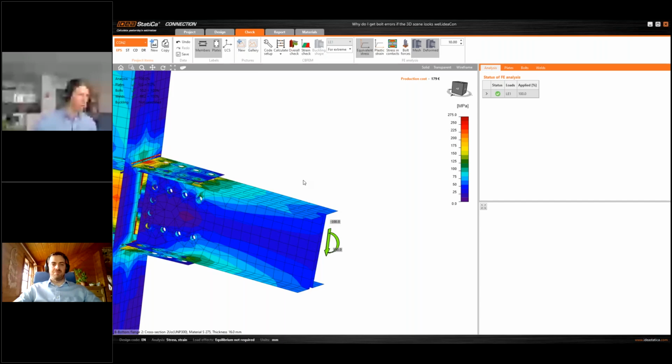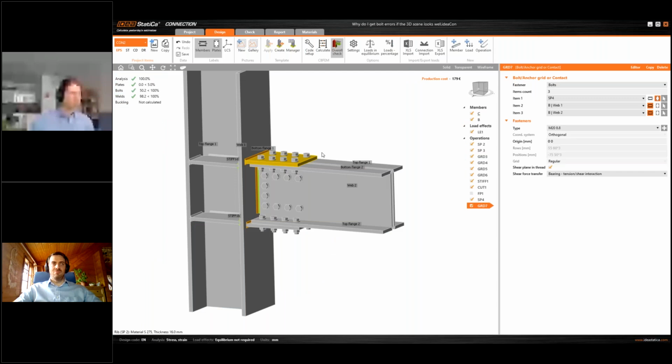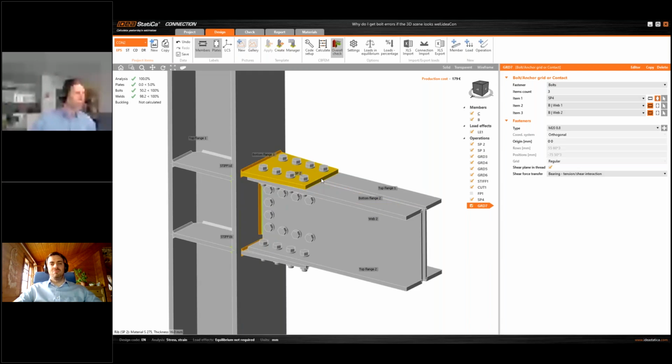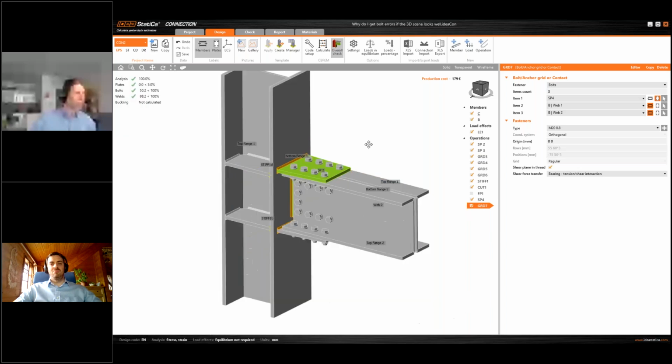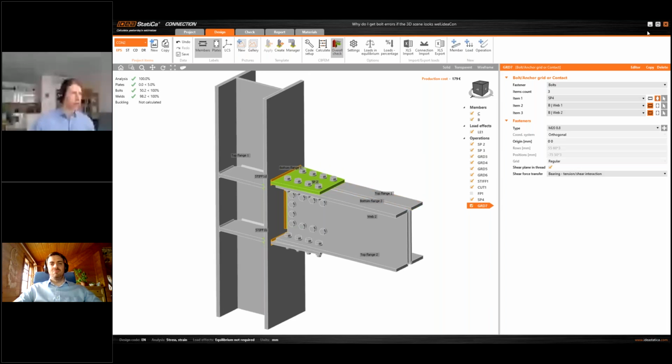For the splices, this takes this phenomenon of using some advanced operation as a fin plate to connect more than 2 plates. That means I'm connecting 3 here. Then it is necessary to use the general operations, the stiffening plates and bolt grids, to model this correctly. Cool, so that was the last word for this.